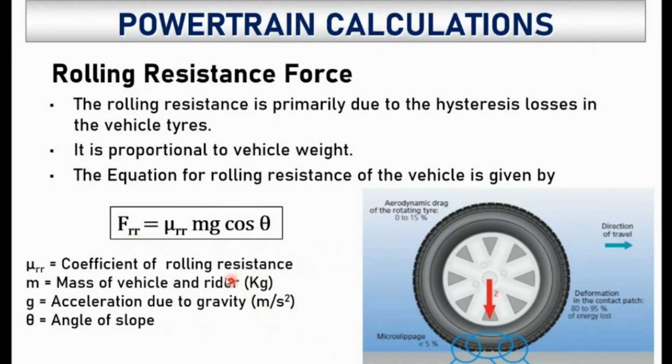Again, for all these parameters, I would kindly suggest you not to search just web pages to get the rolling resistance data. Rather, try to find what is the standard that I should refer to get the coefficient of rolling resistance data.